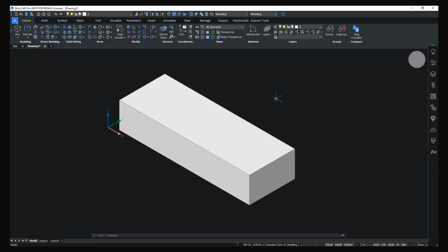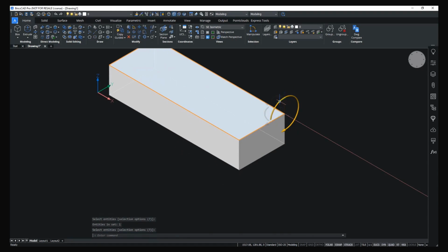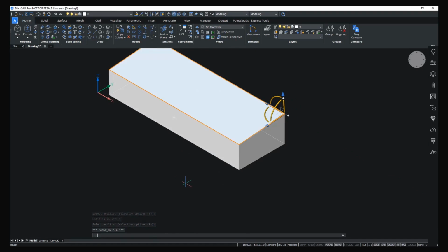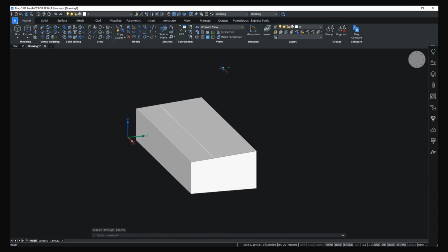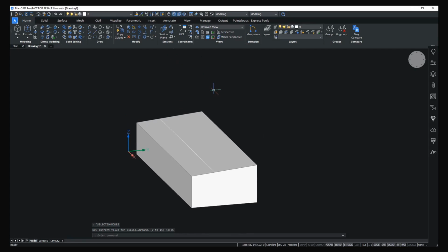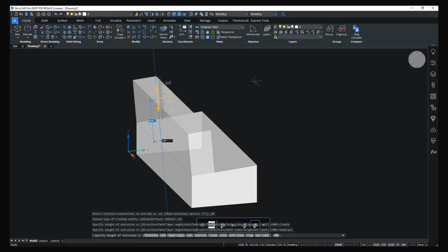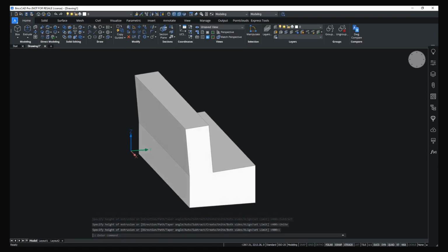In last week's webinar, we talked about things like the manipulator, which also works in 3D. So I can use the manipulator to rotate this face here like this. I can also access sub-entities. In the case of a solid, sub-entities would be edges and vertices and faces. So I can use this edge to create a new line here by offsetting it. Or I can automatically detect boundaries between 2D and 3D geometry like this here, and use it to extrude upward as well, like this.